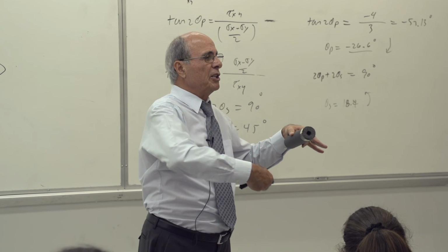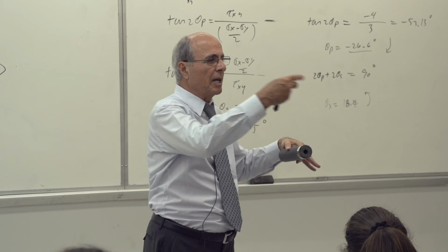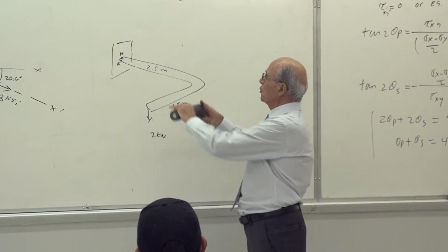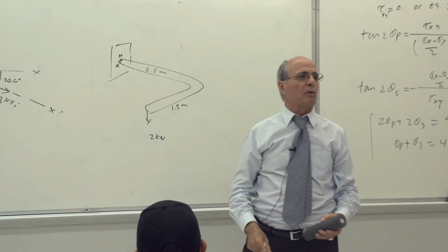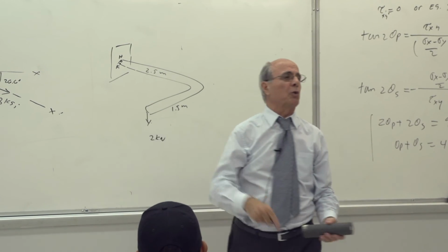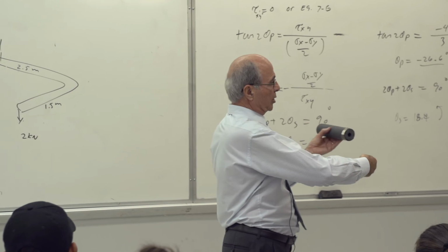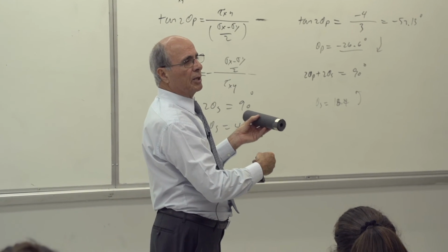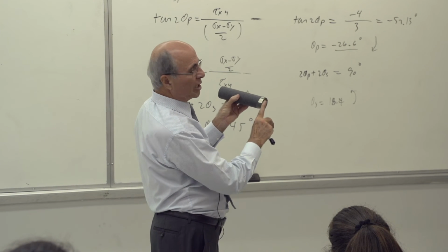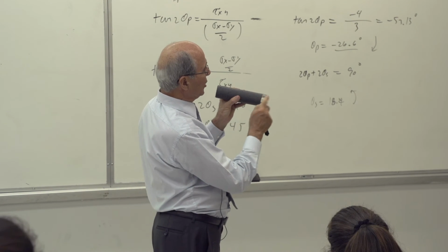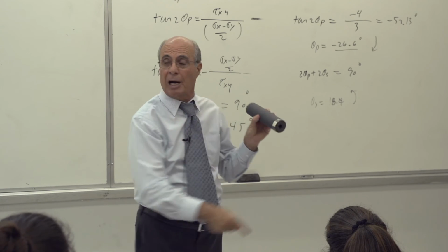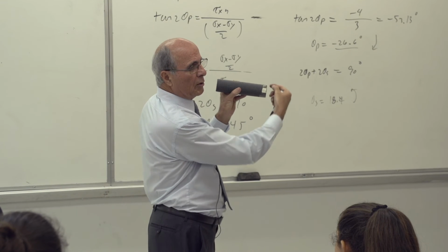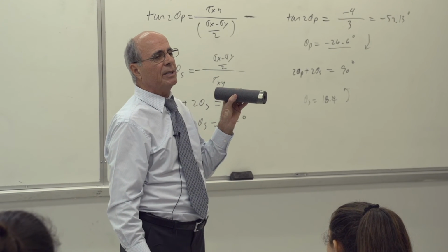In chapter 3, there was torsion there, yes, torque there, yes? There could be here, look at it. If I put this load here, this rod is going to turn this way, yes or no? For that rod, that is a torque, is that correct? So the torque is either clockwise or counterclockwise. If it's going this way, the action, if you are looking at this point, goes like this. So that's your tau xy, you see that? It doesn't matter. You look at the point, and you draw your tau this way or that way. That's Tc over J.